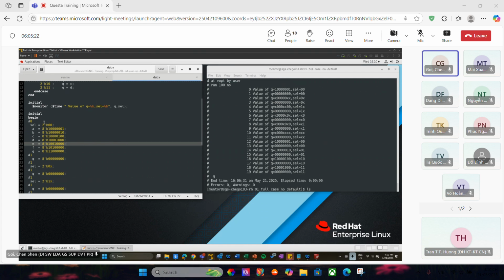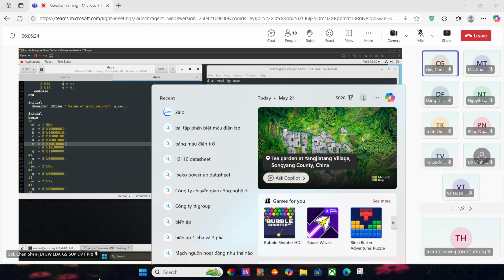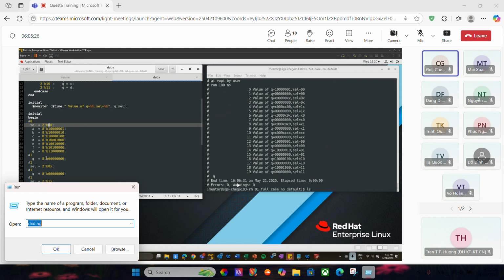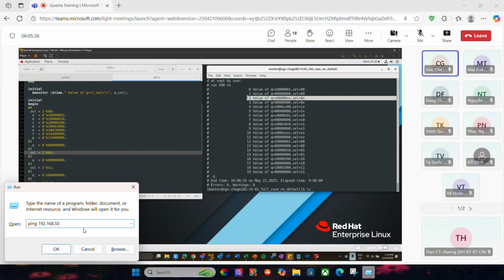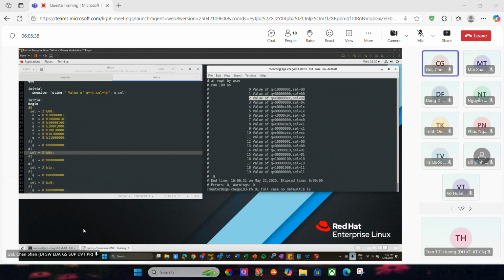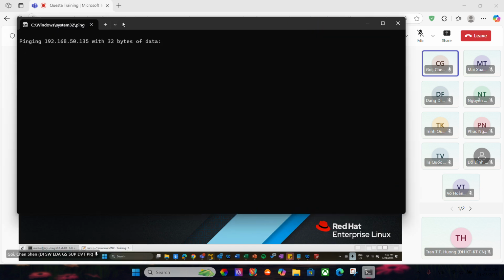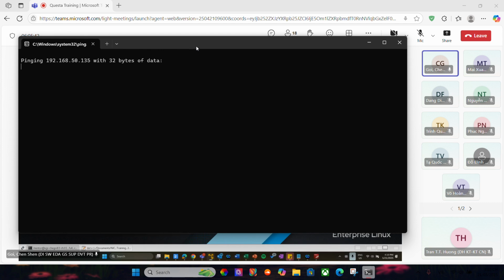You can see when we set the select to 0, 0, we also set the output to be 0 first, and then we set the select to be 0x at 2 nanoseconds timestamp. And then you'll see what is the value of the output Q.